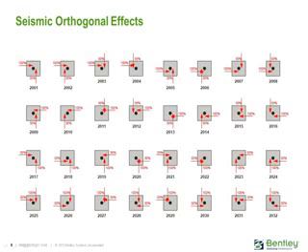In certain circumstances, you may be required to incorporate the orthogonal seismic load effects as necessary to meet the intent of reference standards such as the ASCE 7. Now in our sample STAAD.Pro model, we've already created seismic load items to represent seismic in the positive and negative global horizontal axis direction, also considering the positive and negative effects of eccentricity.